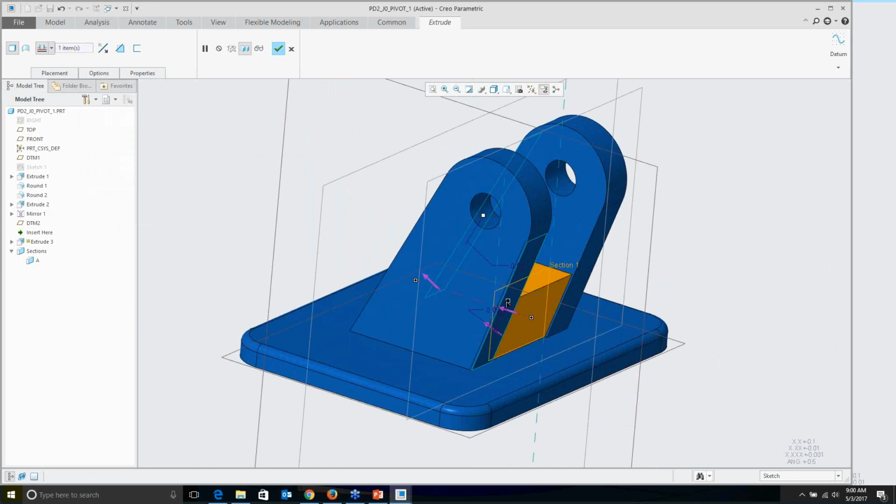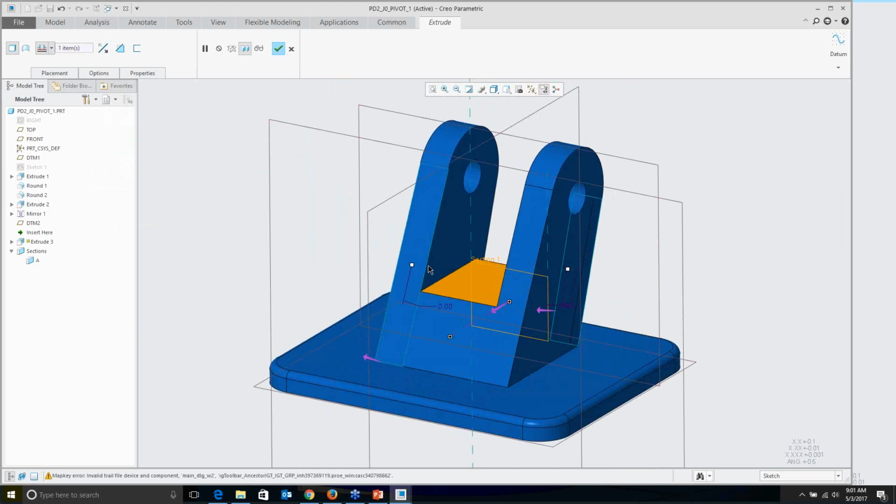And now I could say, hey, let's offset my extrude based on the profile of that selected reference, right? And I want to offset it back by a certain amount. I'll say, I don't know, that's going to be 0.25 over here, and same over here as well. So I can basically push it back inward like that, right?